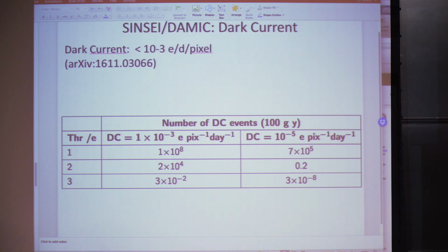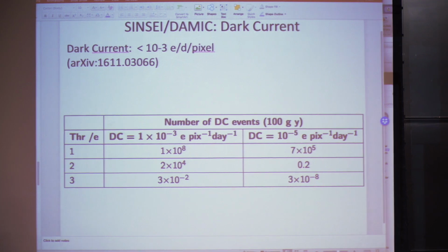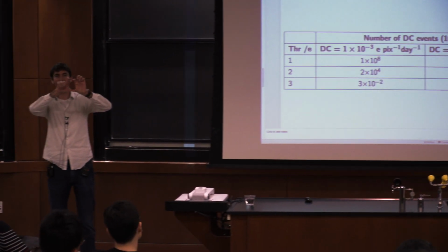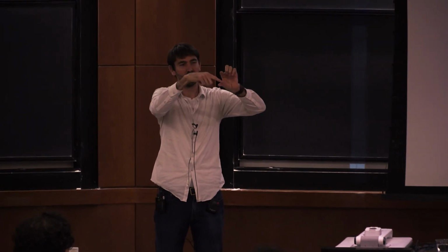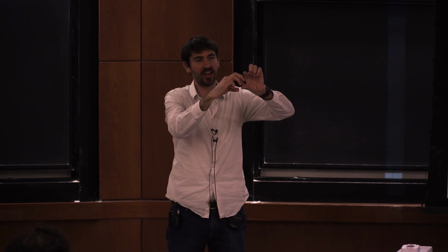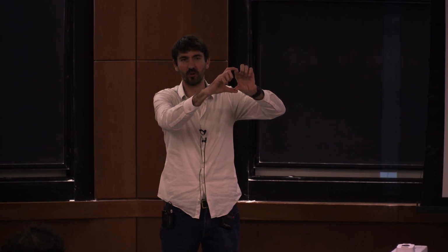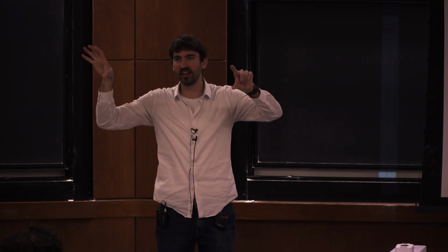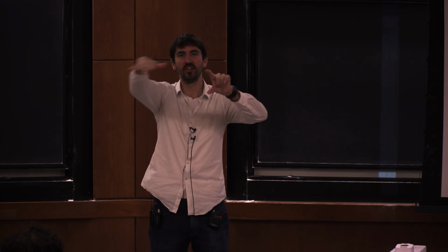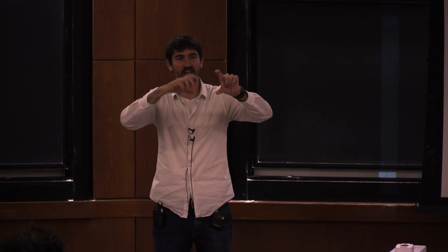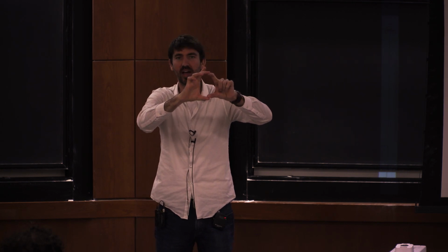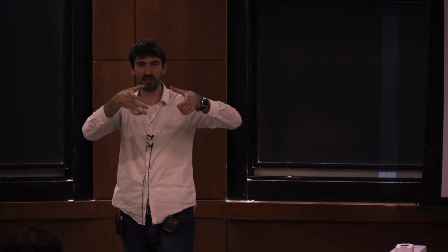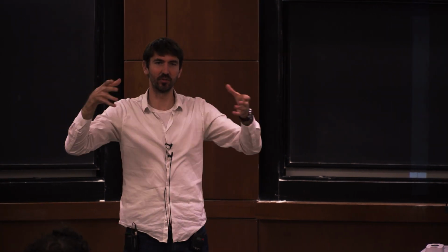So do you guys know how CCDs work? Well, OK. So CCDs are just little ionization detectors. And then, so you produce, it has a pixel. You produce, let's say, 1 electron hole pair, and an electron gets stuck here. So you have, let's say, 10 to the 6 of those pixels in an array. And the pixel has pretty huge capacitance, charge capacitance. It's a big thing. Charge capacitance scales with area.